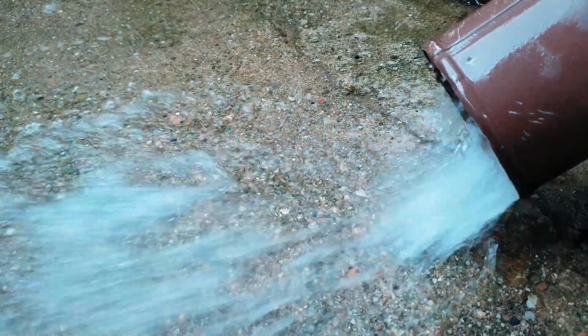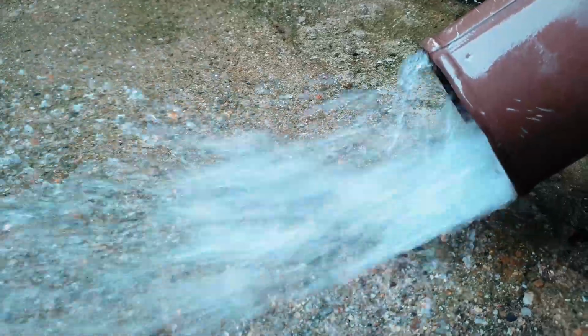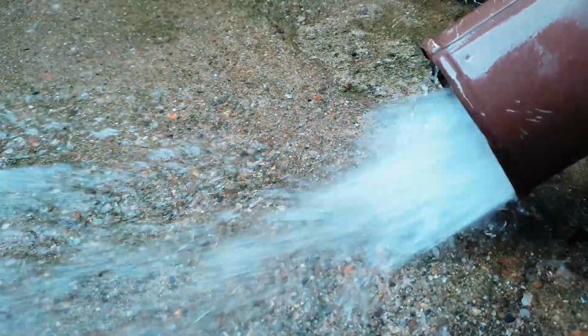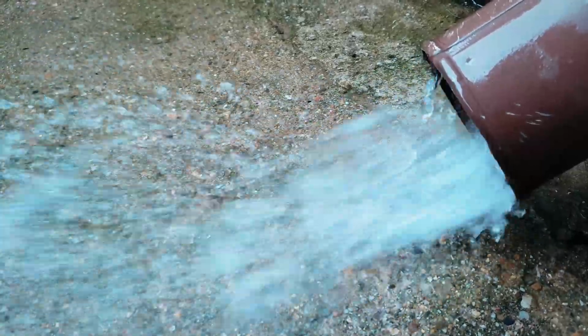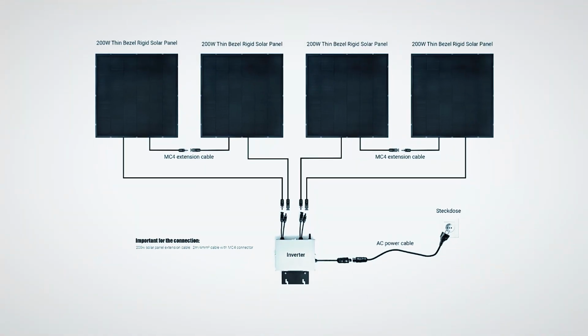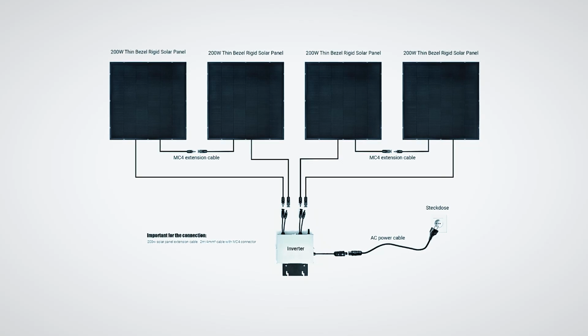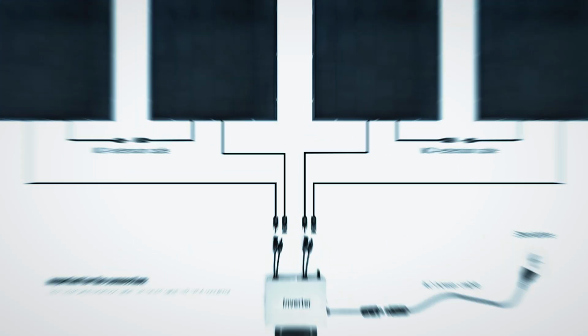When connecting panels in series via solar panel connectors, the voltage of all panels are added together. This means that the total voltage increases while the current stays at the panel with the lowest current strength. In the case of water in a pipe, you increase the potential pressure, but not the actual water flow rate.